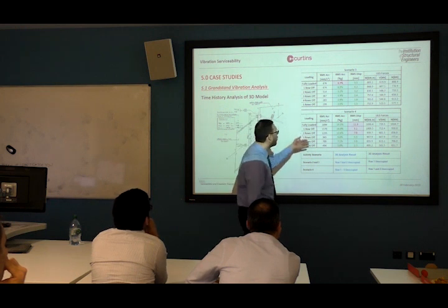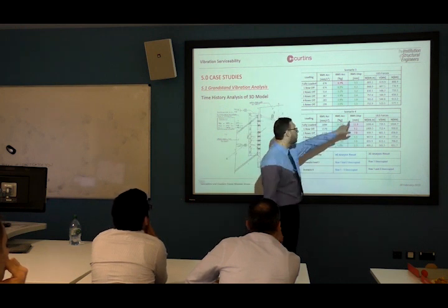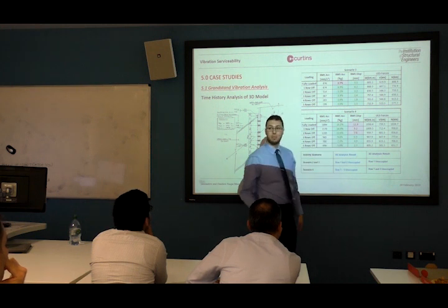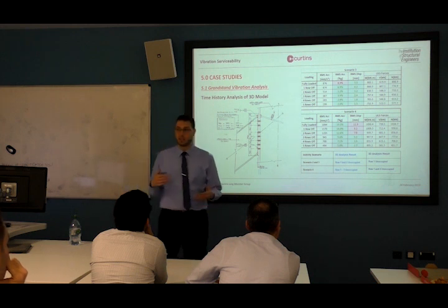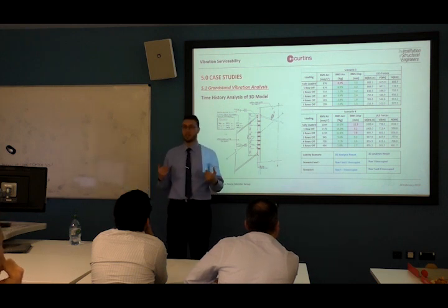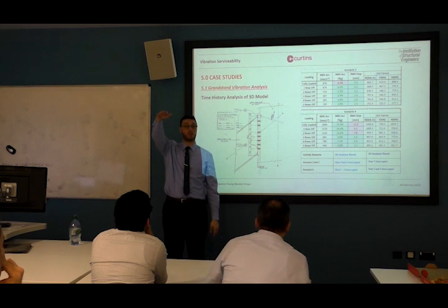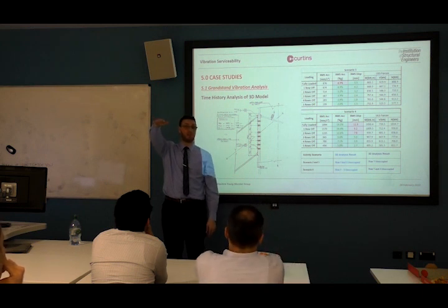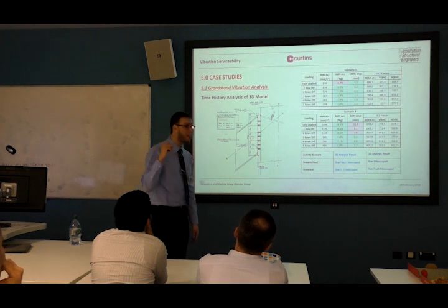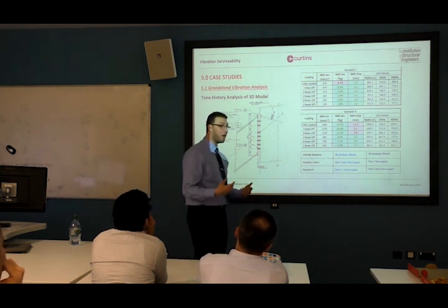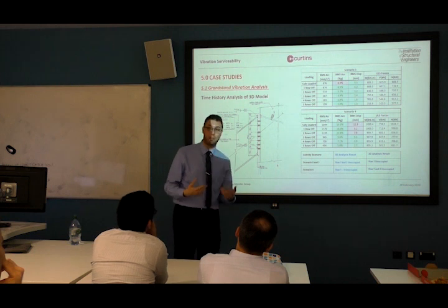Now, in scenario 4, the governing problem was the dynamic displacement, because if you are sitting in the second tier and the third tier is moving in front of you, you will not feel comfortable actually. So if it's moving more than 7 millimeters, the crowd will start feeling panic actually.